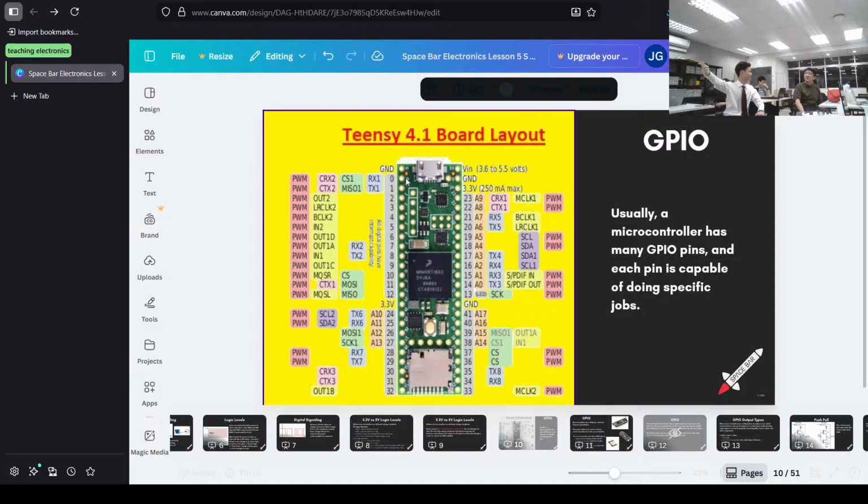The name for it in ESP is called GPIO matrix. IO mux also. Same thing. Different microcontrollers support this differently. The STM32 has a different IO mux also, but essentially can do things with certain caveats. So you always must read the caveats. That's why it's very important to read the data sheet, but for now we won't go through that. Okay, skip this.